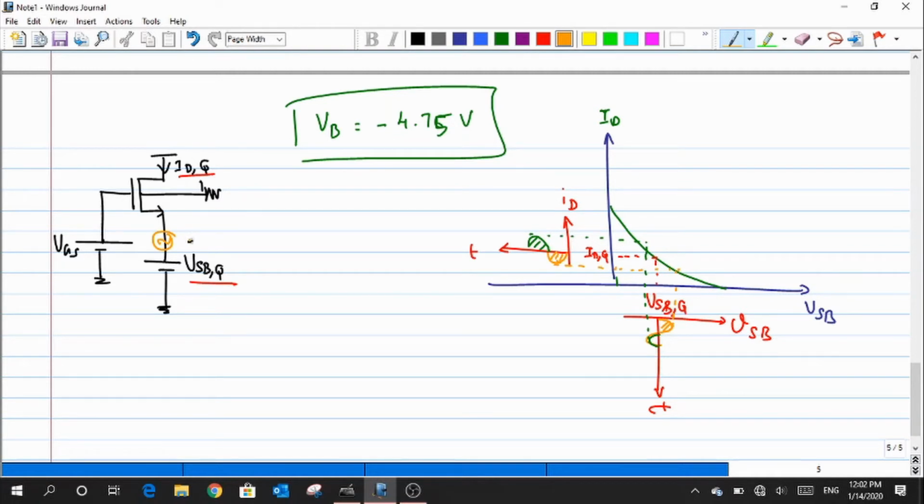Yeah. So this wiggle is what I have to mark as small signal VSB. Is that clear? And due to which the current right now would turn from this to small ID. So because of this addition of wiggle, there is a change in the current, and that change in the current is being marked with small ID.